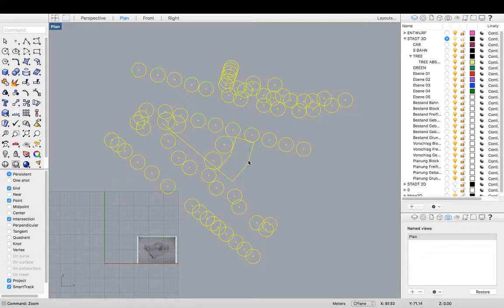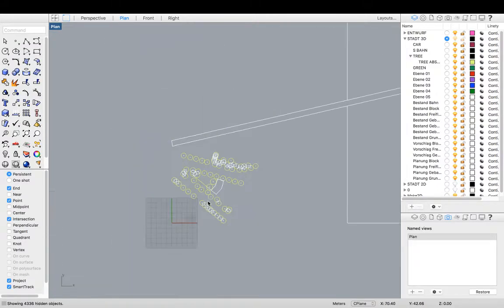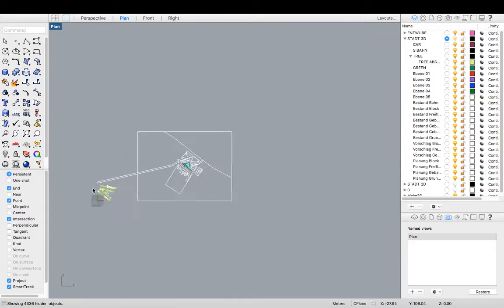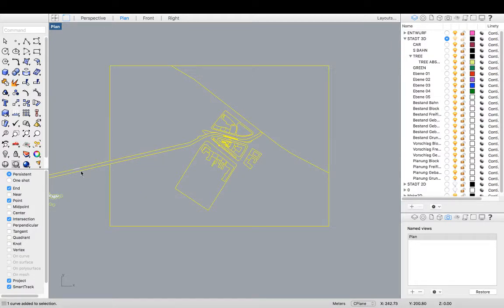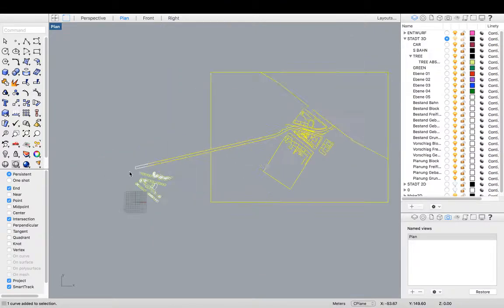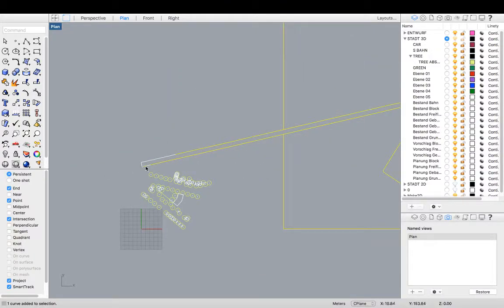I'm just going to go ahead and group, after every Make 2D command, just group all your objects so you have them together to make it easier to select. And now type in the command show and we'll see the rest of the graphic appear. We can actually go ahead and group these objects as well. It's easier to do this straight after the Make 2D command, because then everything will be selected.